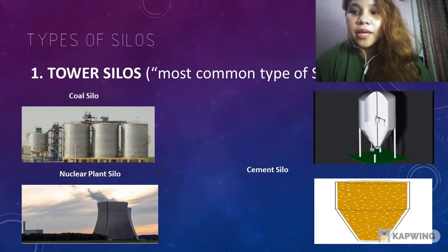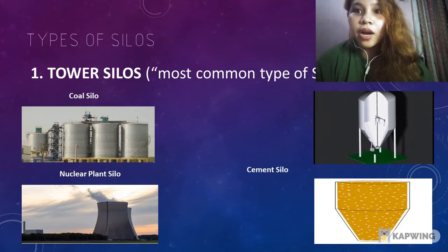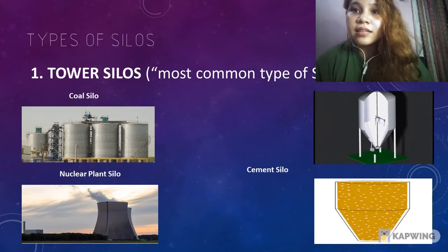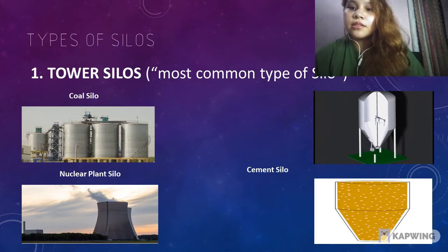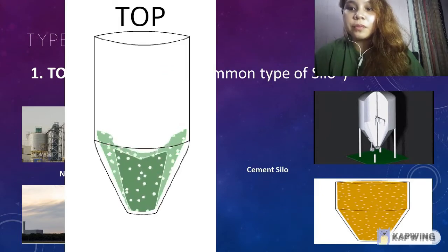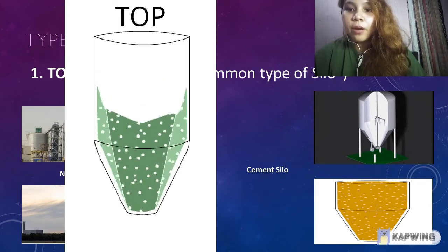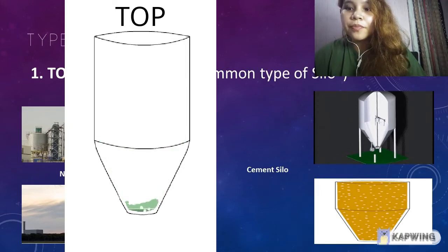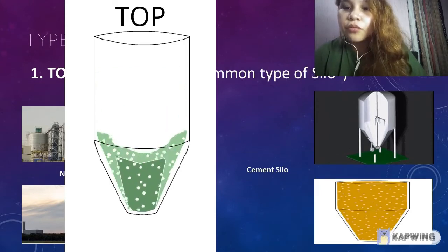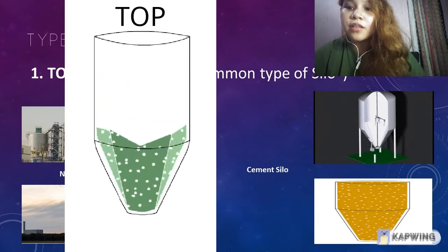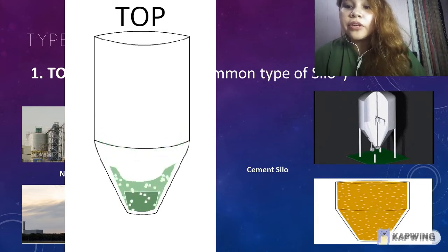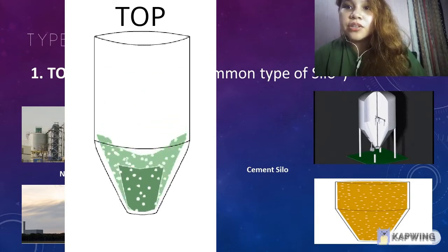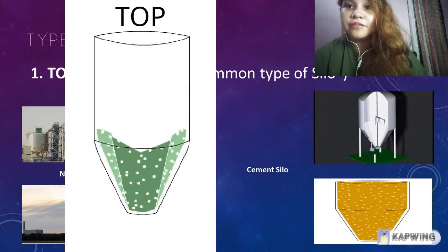Silos can be unloaded into rail cars, trucks, or conveyors since it is hard to do if it is manual. So in most silos, gravity causes grain to flow from the top of the silo and out through an opening at the bottom near the center. As grain flows through the center or the auger, it forms a funnel shape at the top of the silo. And if workers stand at that location, flowing grain can pull them into the mix, causing injury or loss of life.